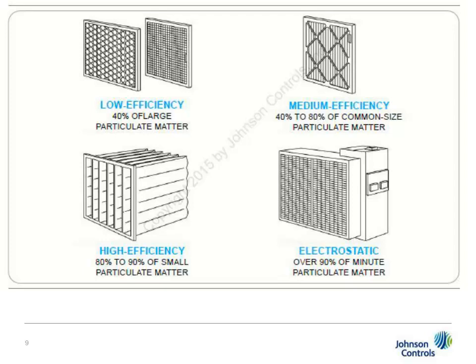For more serious filtration, we would be looking at the higher efficiency 80% or greater filters. The bag filter in the lower left of our illustration provides more serious filtration. Not shown in our illustration are the HEPA filters, or high efficiency particle arresters. These filters are used in clean rooms, but are available for use in residences as well as in commercial buildings. Often these more efficient filters are so expensive that we place less expensive, lower efficiency filters in front of them so as to avoid replacing the more expensive filters as often. Electronic filters, as we see on the right bottom, charge the particles with one electrical charge and then attract those particles to an element containing the opposite electric charge. All filters must be properly installed, maintained, and monitored if they are to perform their intended function.